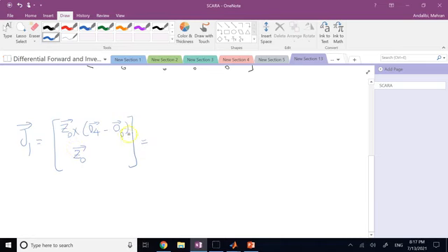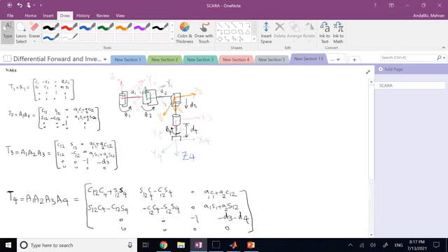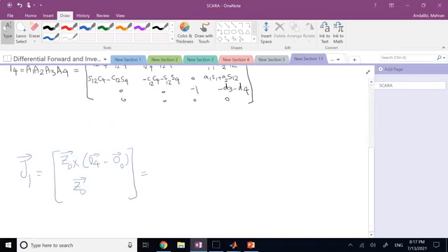Okay, where do I get Z0 and O0? All of it from T0. Again, there is no T0. And you know, whenever you're down to this very first one, your Z is always the Z that we always have in our XYZ coordinate, 0, 0, 1. And your O0 is simply all zeros.